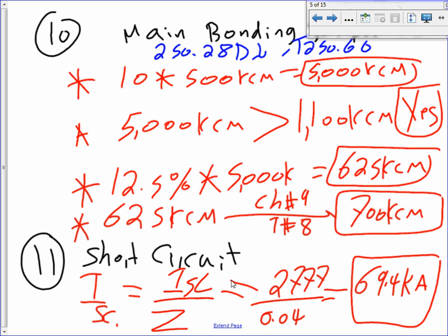Now the fuse in the secondary, what was the size of the fuse in the secondary? 4,000, right? My fuse is going to be 4,000 amp load current and 85,000 interrupting rating. Why 85,000? Because the next standard after 69.4, I believe, is 85. There's 65 and 85,000. How do I know that? That's in the Cutler-Hammer and Square D literature. They tell you.